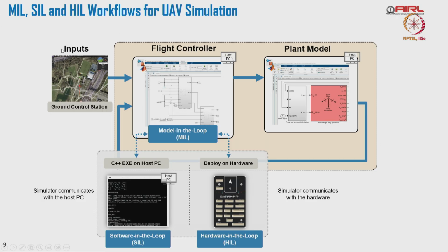If you talk about the software in the loop, hardware in the loop workflow, you need input. The input is going to come from your ground control station, right? Basically that is a key factor. A ground control station will define your mission, right? Here is the mission. Let's say you want to spray on a specific agriculture land, 2 acres of land. Then the ground control station will define the boundary region of that particular agriculture plot. This is your speed limit. This is your height limit, right?